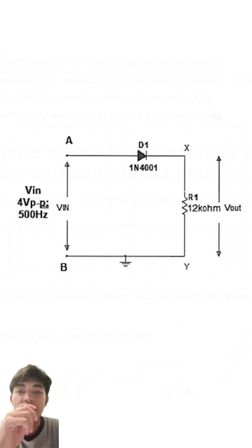During the negative half cycle, the diode becomes reverse biased and blocks the current. As a result, the output across the load is a series of positive half sine waves with gaps in between where the current is blocked. This creates a pulsating DC output.